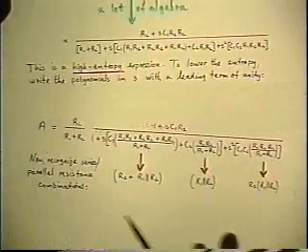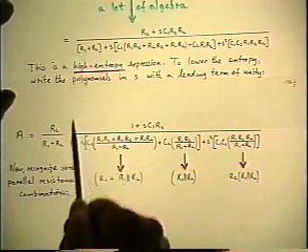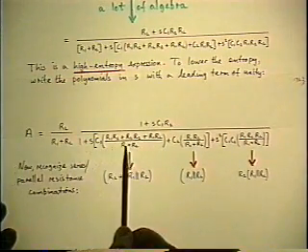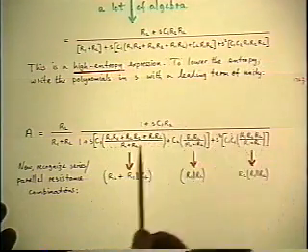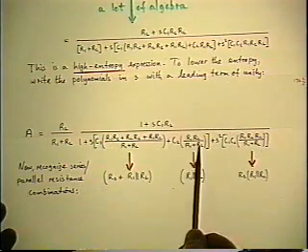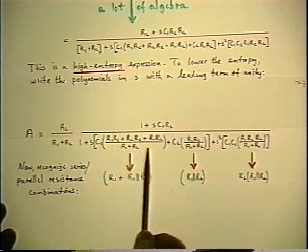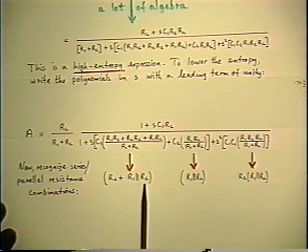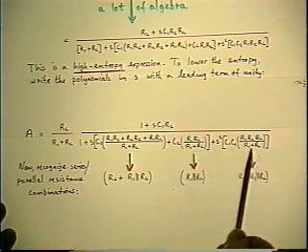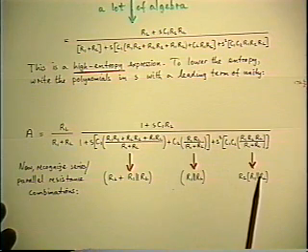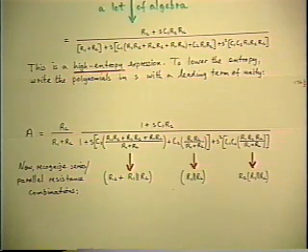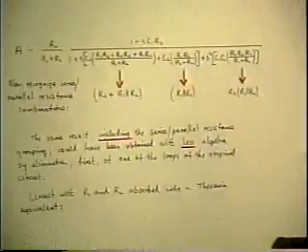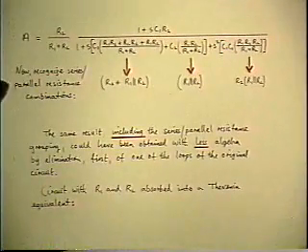And the way you get that, of course, is you pull out R1 plus RL from the denominator, which means you have to divide it into the second and the third coefficients. And then, if you gaze at this combination long enough, you can determine that it's this series parallel combination. And the same combination shows up in the other two terms as well. So by putting mental energy into it, you can lower the entropy. However, that's more work than necessary.